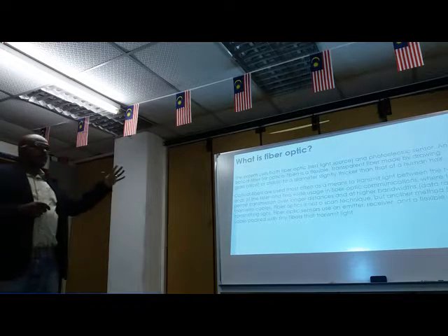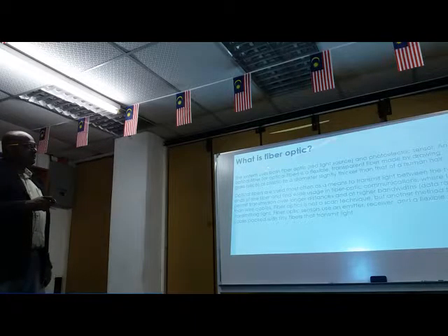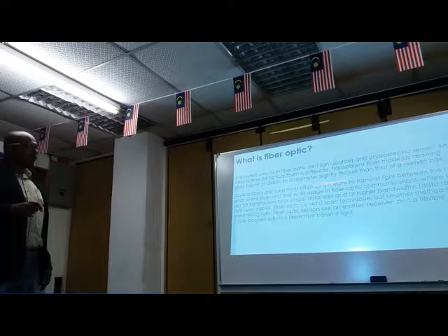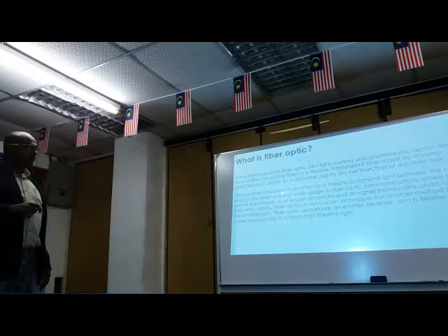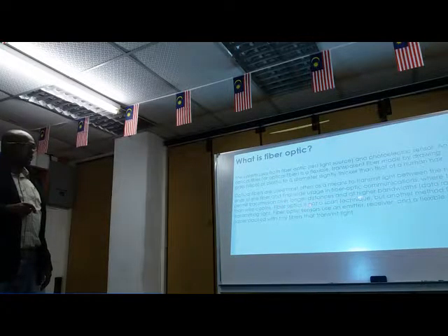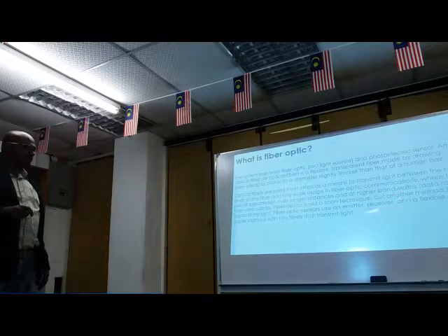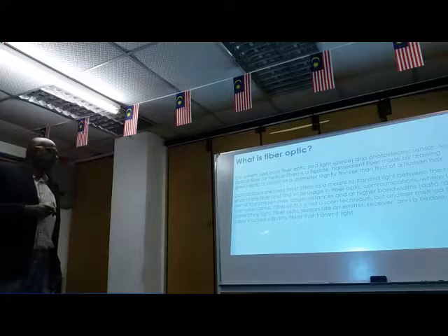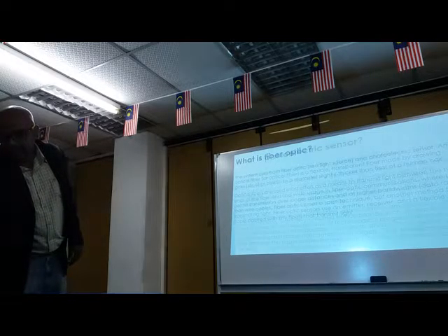So, an introduction to some of the items that have been used in this project. What is fiber optic? The system uses both fiber optic, a red light source, and a photoelectric sensor. An optical fiber is a flexible, transparent fiber made by drawing glass or plastic to a diameter slightly thicker than that of a human hair. Optical fibers are used most often as a means to transmit light between the two ends of the fiber and have wide usage in fiber optic communication, where they permit transmission over long distances and also have higher bandwidth. Fiber optics is not a scan technique, but it's another method for transmitting light. So fiber optic sensors use an emitter, a receiver, and a flexible cable packed with tiny fibers that transmit light.